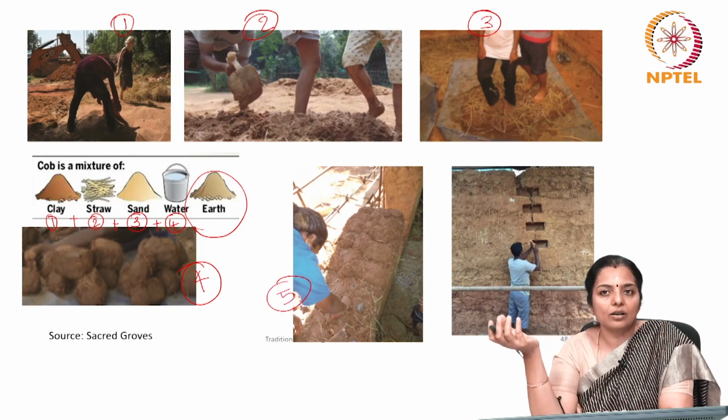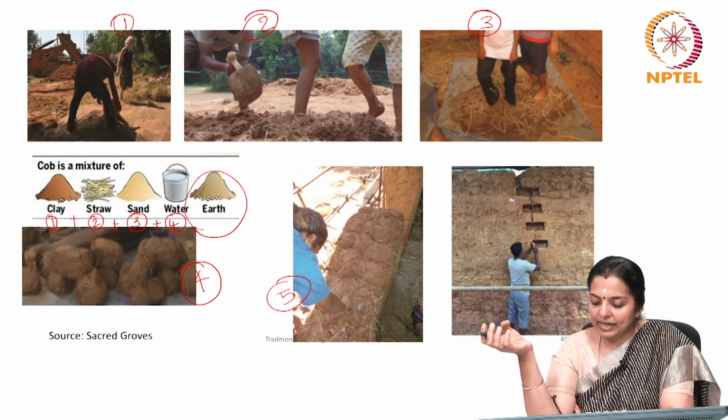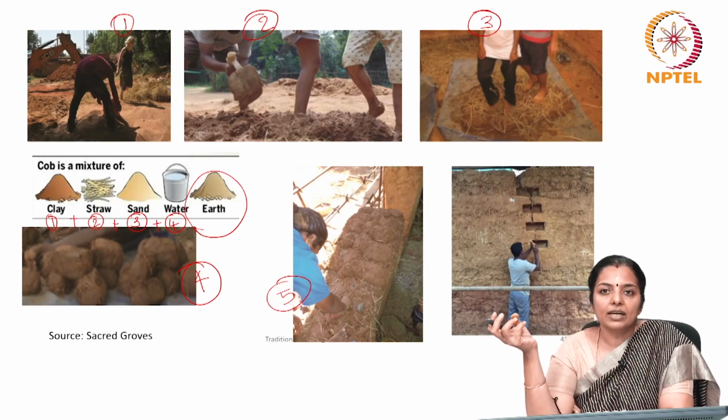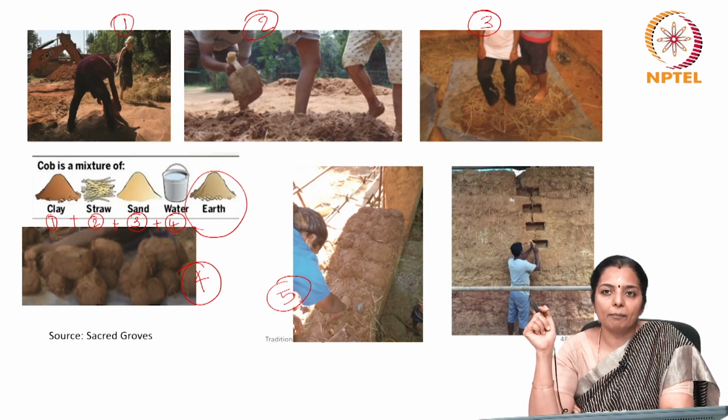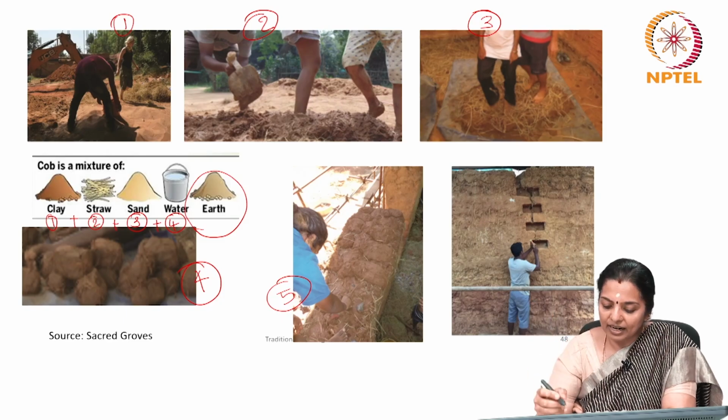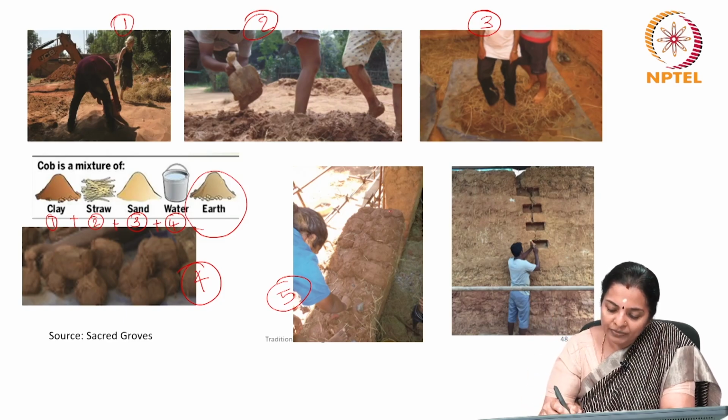So, once the cob ribs and spine have been added, compress the brick using a spiky element like a stick or even some shoe or something like that to combine them into a single layer rather than single blocks. So, don't make these only as blocks like cob rounds like this.